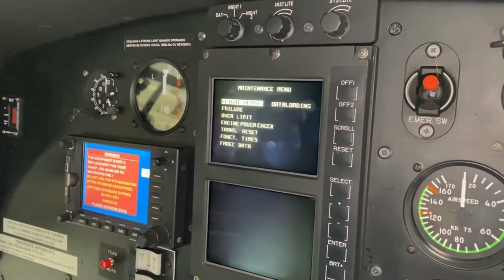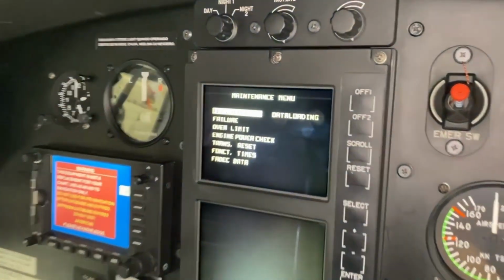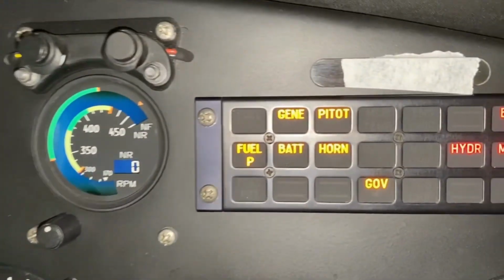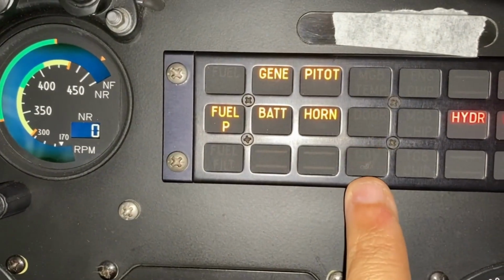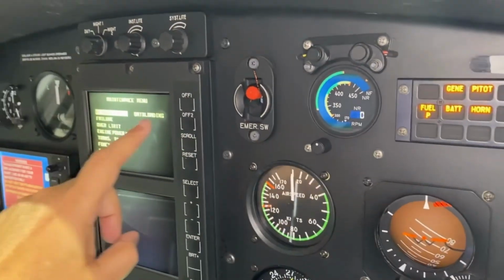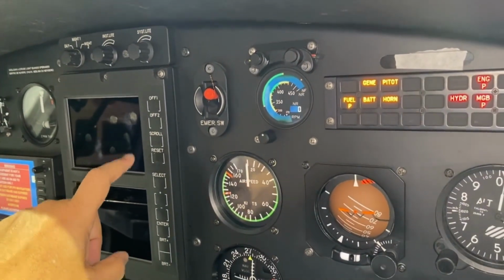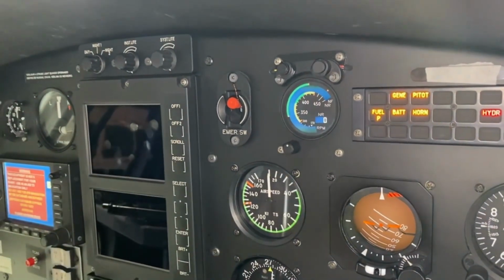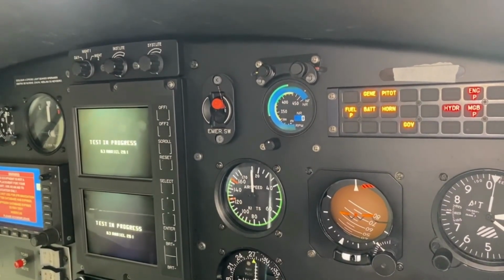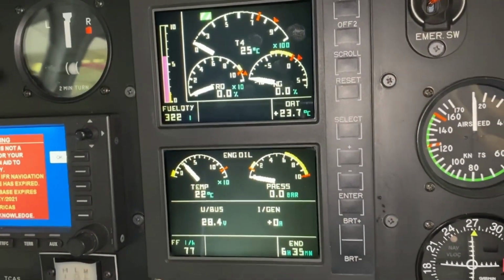Well, here is one more important piece of information for you. Whenever the VMD system is in the maintenance page access mode, it is completely normal for this GOV indicator light right here to keep blinking continuously. Alright everyone, I'll show you that if I reset the VMD to normal, that GOV light will stop blinking. I turn off both VMD channels and then turn them back on. The very moment I turn it on, it should stop blinking. And look at that, it has finally stopped. So now the VMD has returned to its normal condition and operation.